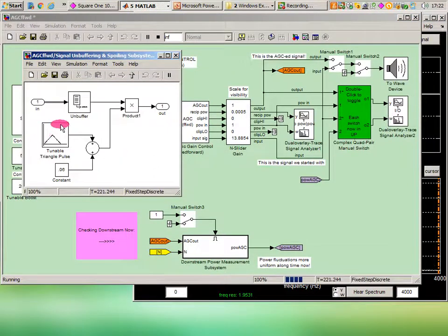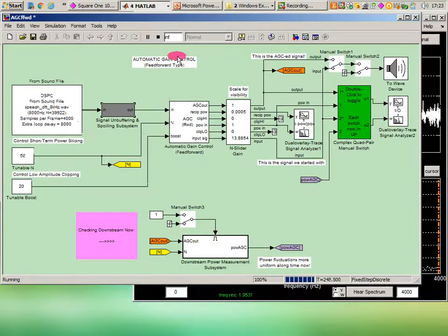I've got here a linear rundown following on to a small plateau, and here's the point: it's all multiplicative, so the original waveform is not having any noise added to it or anything else like that. It's just getting this multiplication operation which is most inconvenient and most disturbing. Of course, if we were in the fortunate situation of knowing what this multiplication factor is, all we'd have to do would be to divide it back out and we could recover the waveform. But of course we don't have that knowledge, and the AGC block has to operate in ignorance of whatever might be concocted here, not just our simple little model.